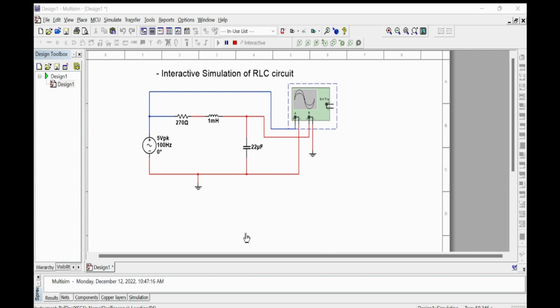If you want to read them more clearly, this is the time base, the time scale, as you usually use on the oscilloscope in your labs. Just click the time per division scale. Now the waveforms have expanded over the window, and this can be read more clearly.